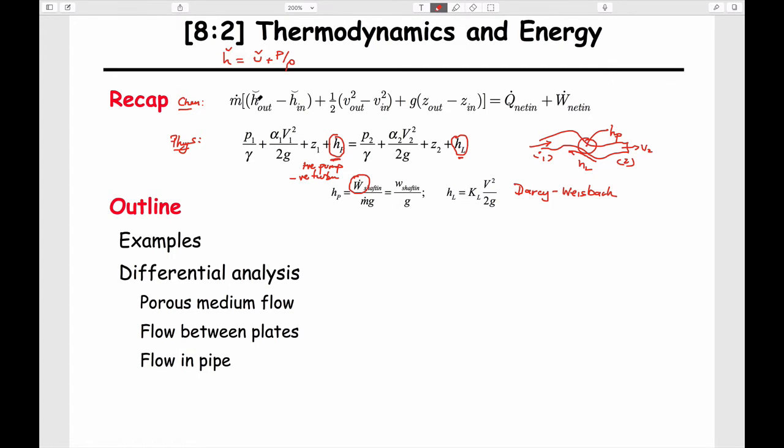But the units of enthalpy have to be equal to energy per unit mass. Did I say volume? And so if you look at the units of this, this is a Newton meter. I'm running out of space, but if I go over here to keep it going, a Newton meter is 1 kilogram meter per second squared, right, this term here. And then meters and kilograms from the remainder. And so this is equal to units of meters squared per second squared. A strange number, but of course it's the same as velocity squared. Velocity is meters per second, velocity squared is meters squared per second squared. And so clearly these have to be the same units to be able to match up.